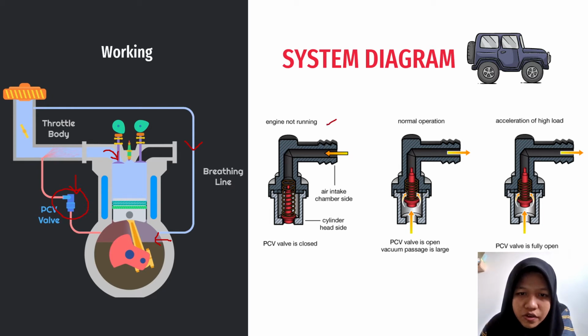When the engine is not running, the PCV valve is closed. And in normal operation, the PCV valve is open. Vacuum passage is large. Then the last one, when you accelerate or at high load, the PCV valve is fully open.